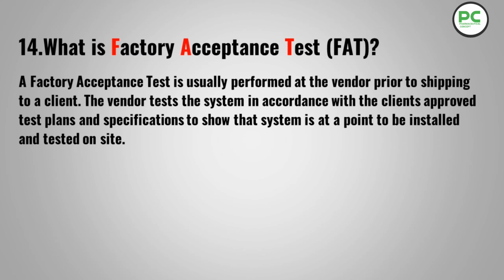What is factory acceptance test (FAT)? A factory acceptance test is usually performed by the vendor prior to shipping to a client. The vendor tests the system in accordance with the client's approved test plans and specifications to show that the system is at the point to be installed and tested on site.